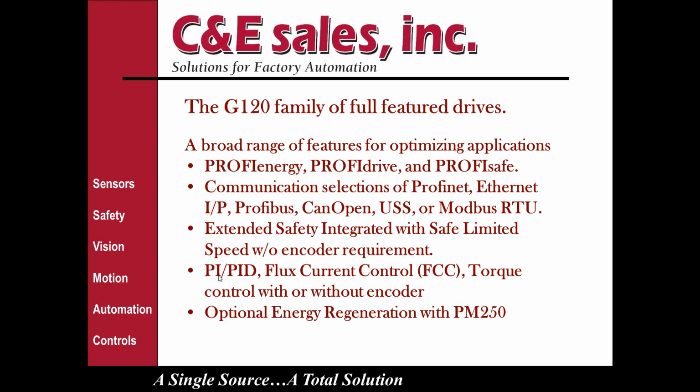We have a broad range of control options available in the G120 line. PID for process applications, flux current control for monitoring or controlling the amount of current that you send out to a drive, and torque control with or without encoders. And then with the new PM250 line, we can do energy regen back to the grid again.